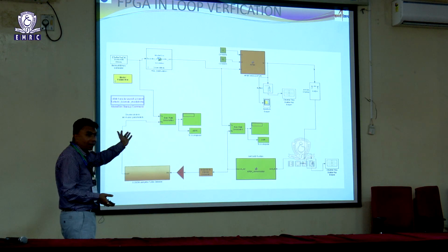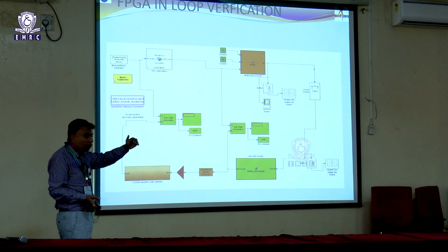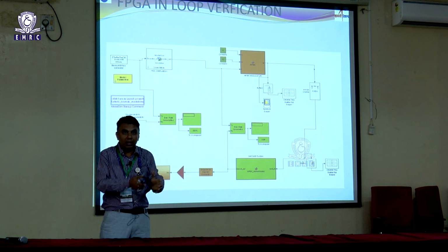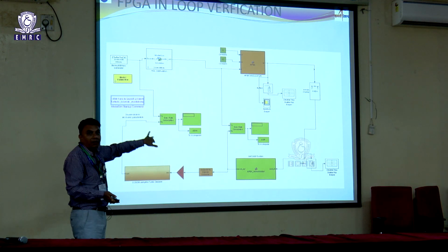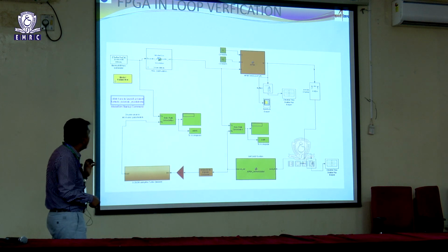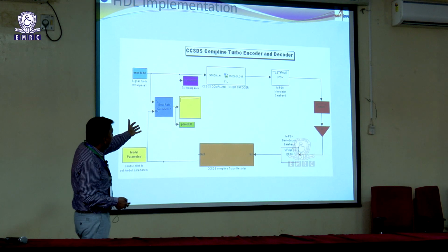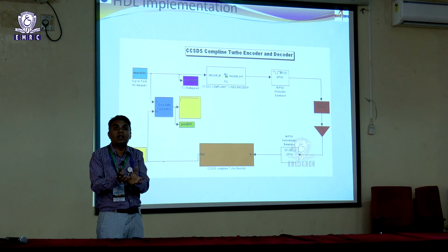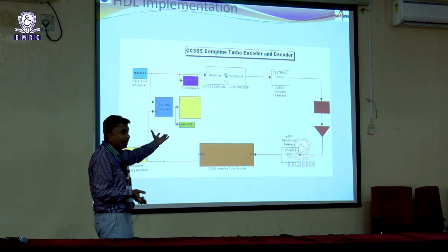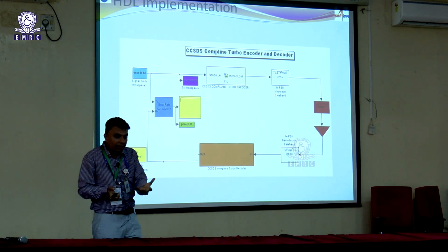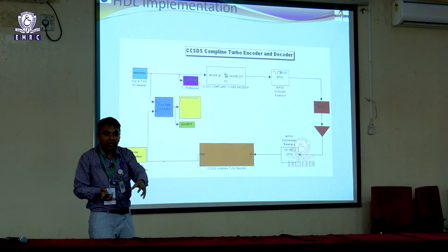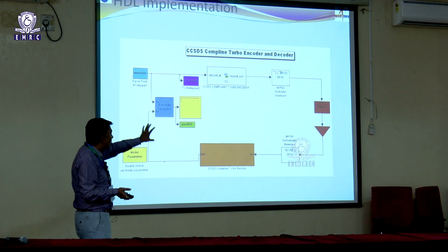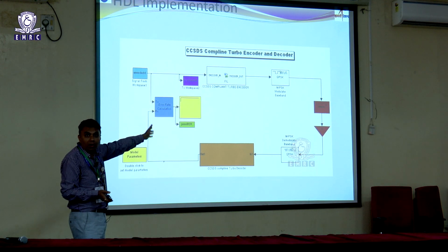This is now a standard practice called FPGA in loop, where some code is in the Verilog or VHDL domain and some modules are in the Simulink domain, integrated together, and in closed loop you can verify the design. Second is the HDL board itself. Although the code will be verified, I want to verify it on the hardware board itself. That is called FIL, where your FPGA board also comes into the Simulink environment, where we can download your own HDL code and put the FPGA board inside the Simulink environment together. Some blocks, like in this case, we are verifying the turbo code encoder and decoder.